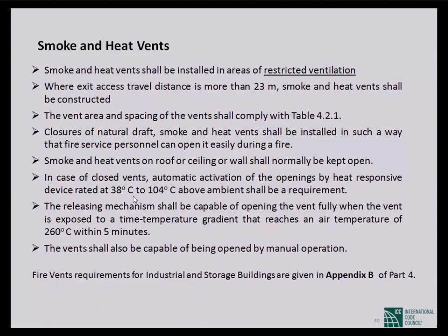When exit access travel distance is more than 25 meters, smoke and heat vents shall be constructed. So this is the one thing you have to construct in the building. First, you have to give the vent for the restricted ventilation area. And the second thing is, if the travel distance is more than 25 meters, you have to give smoke and heat vents so that there will be no accumulation of heat and smoke.